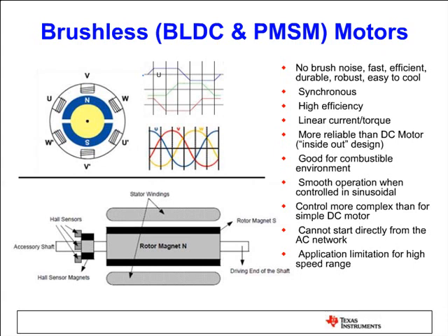And the rotating air gap field is synchronized to the rotor, which means that the rotor follows the rotating field, because the rotating field in the air gap behaves sort of like an electromagnet, and the rotor magnets follow it. So they are synchronized to each other. They are very efficient, and they have very high power density.